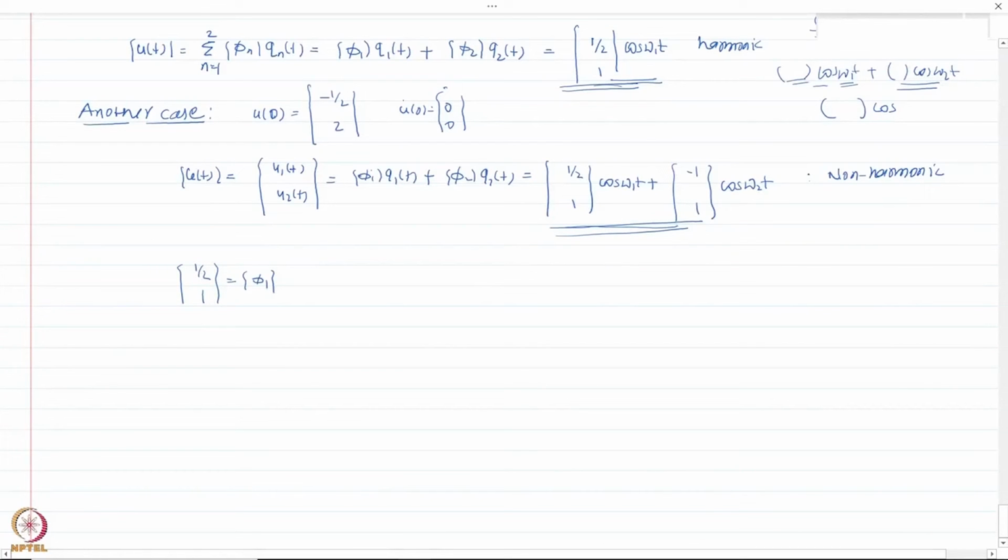By definition, as we have previously discussed, if you assign an initial displacement to the structure according to one of the characteristic shapes, then it is going to respond harmonically while maintaining its shape, vibrating in a particular mode of vibration. So there would be no contribution of any other mode.